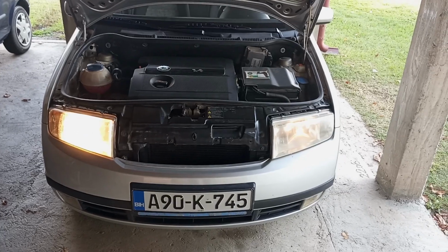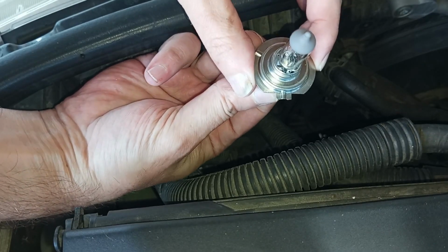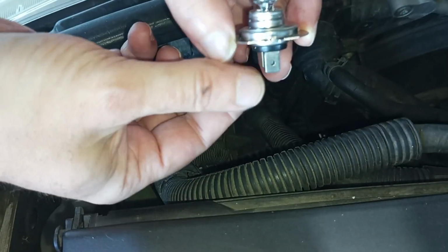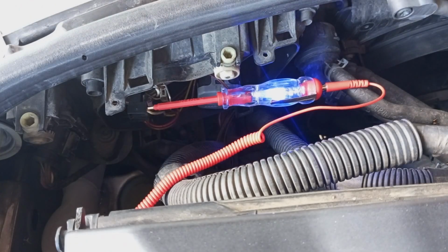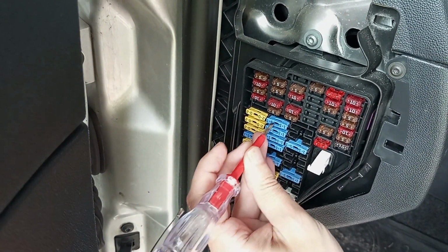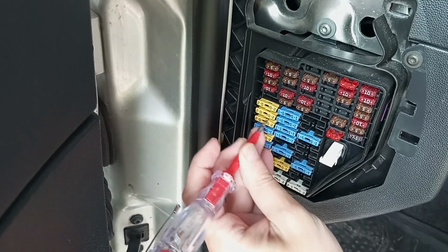You have a low beam headlight that's not working. You change the bulb and still it's not working. The elimination process tells you this. Take the 12-volt tester and start testing from the light bulb connector. Okay, check if there is a power input to the light bulb connector, and then go through the rest of the components. Go first through the fuse, then go through the relay, then go through the stock switch, then go through the ignition switch. It doesn't have to be in this order. With every car, it's a bit different, but the basic principle is the same.